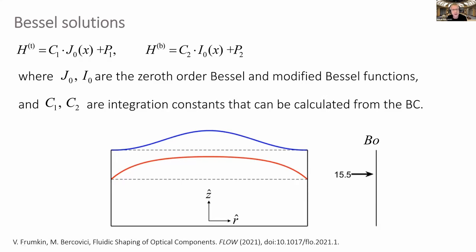And the surprising thing is that two physics from two different disciplines, from fluids and optics, meet very nicely here, in that this Bessel function is the first order correction for spherical aberrations in optics. And these surfaces are typically very difficult to create with standard machining because there are multiple axes required in order to machine this. We get it just by changing the density of the immersion liquid.